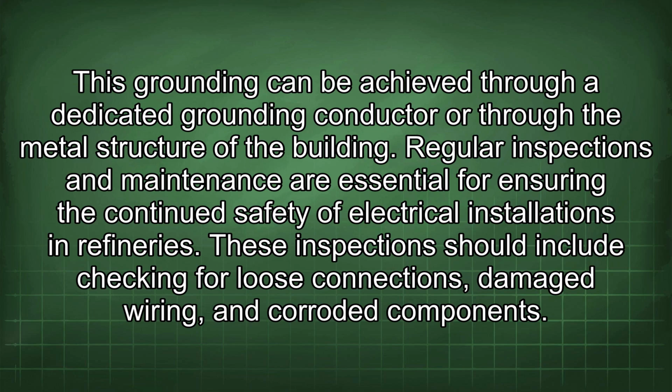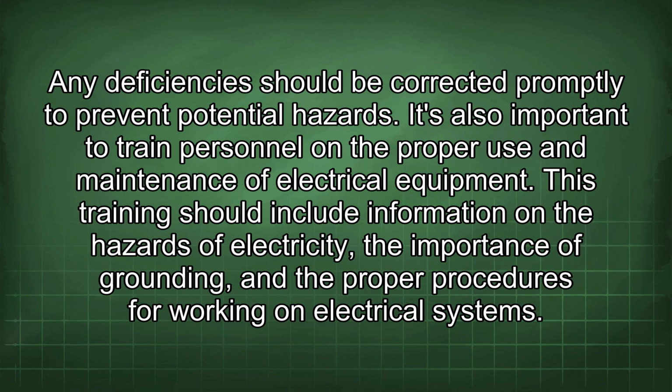Regular inspections and maintenance are essential for ensuring the continued safety of electrical installations in refineries. These inspections should include checking for loose connections, damaged wiring, and corroded components. Any deficiencies should be corrected promptly to prevent potential hazards.